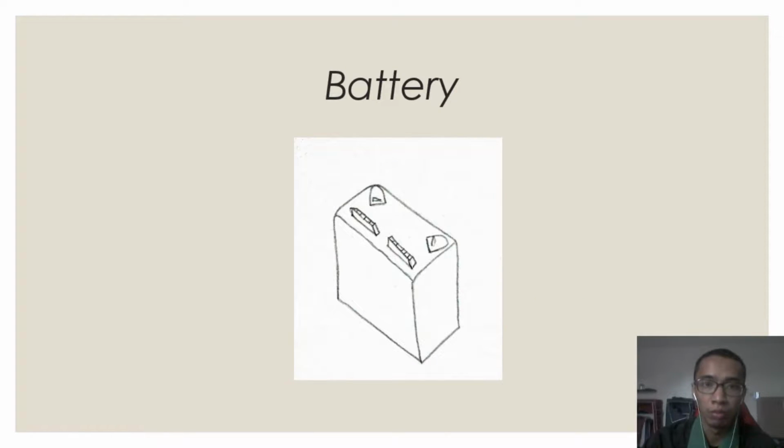Next, the part of the lawnmower that I want to explain is the battery. This battery functions to make the two motors that are connected to the rear tires work. The length of this battery is 230 mm. Its width is 138 mm, while its height is 208 mm. The voltage of the battery is 12 volts and it is mounted on the top of the shield plate.